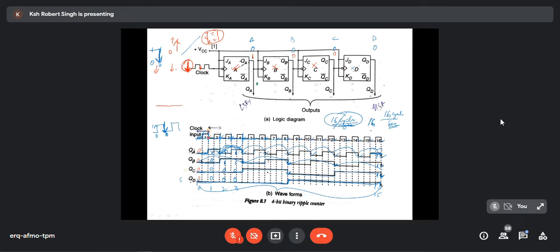This is the clock 0 to 0 transition. It is not going to make this D flip-flop activate because it is not a negative edge trigger. So this output also will be no change. Now the output is 1 0 0 0. It is similar to 1 0 0 0. Now I am in this stage. Now let us think that another negative edge has come.